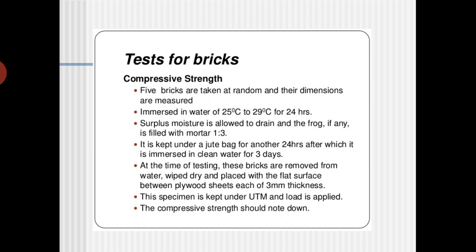If it is more than 30 degrees centigrade or less than 25 degrees centigrade, it is not recommended. The standard code says that the temperature of the water should be between 25 to 29 degrees centigrade, or up to 30 degrees centigrade. So make sure that the temperature is between 25 to 29 degrees centigrade.